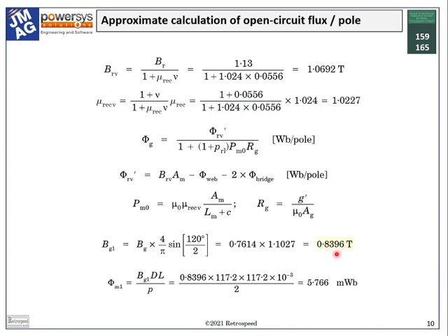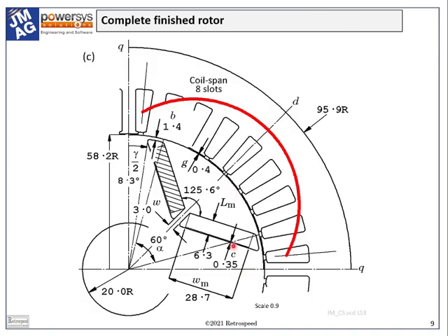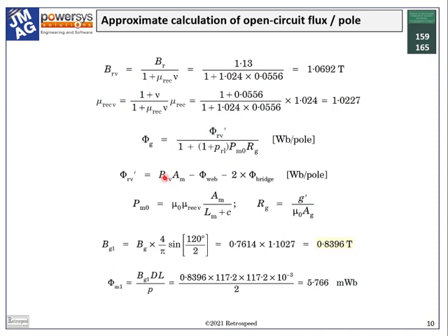It's worth pointing out a few details. The clearance gap is dealt with by the artifice of an equivalent magnet whose properties are given by these two formulas, where nu equals C over Lm, the ratio of the clearance gap to the magnet length in the direction of magnetization. When this ratio is small, let's say less than 0.1, the equivalence is very good. And here we have nu equals 0.0555 or 1/18. So we can safely rely on this simplification.